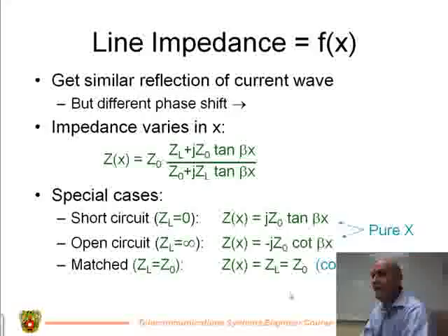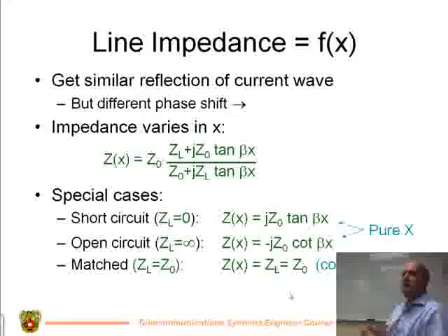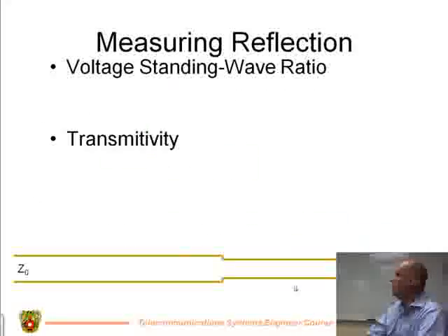If they're not the same, and you can't make them the same, then you have to compensate by doing what's called a quarter wave matching filter, or there's a thing called a Balun. There's a couple other things, and we'll actually look at those here in just a minute once we figure out how. We need a little bit of stuff to understand that first.